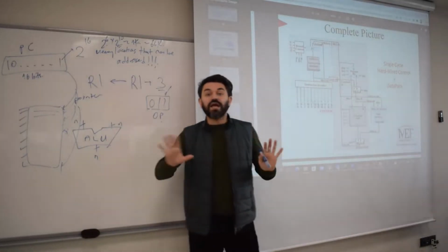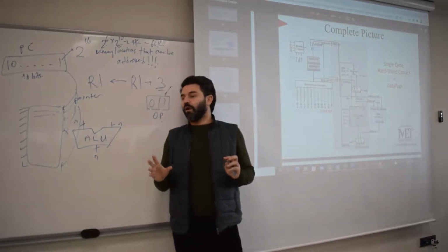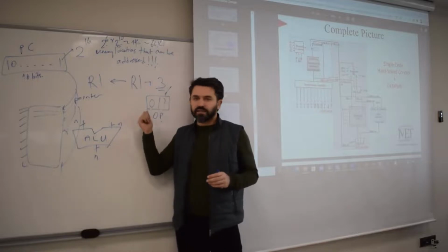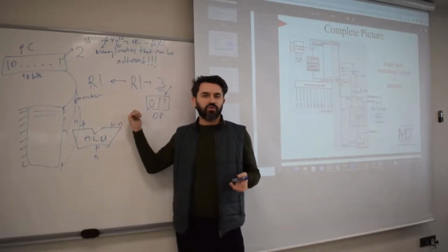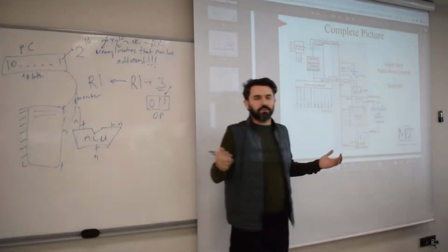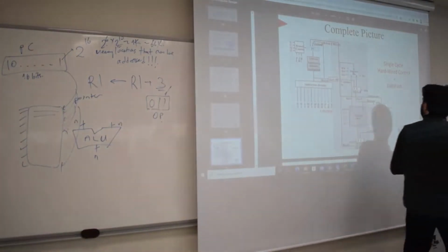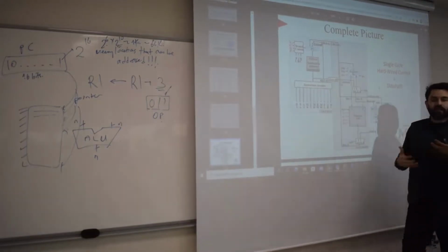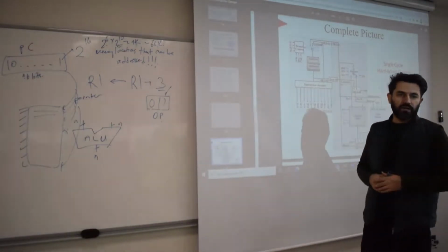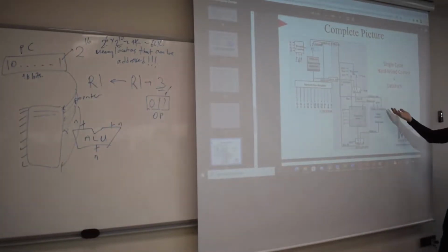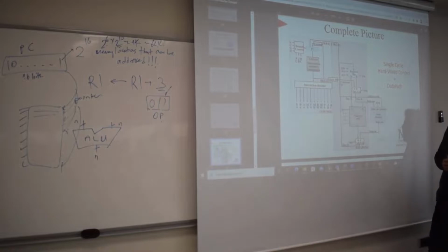But this is again free. Don't take it as the only way. That's not the only way. You can actually put a sign extension in your design and make negative numbers a possibility. That can also be done. There's no harm in that. But I just assumed that I would like to add like 6 and 7 to my architecture. That's why we assume, like the book assumed, that to be a positive number.